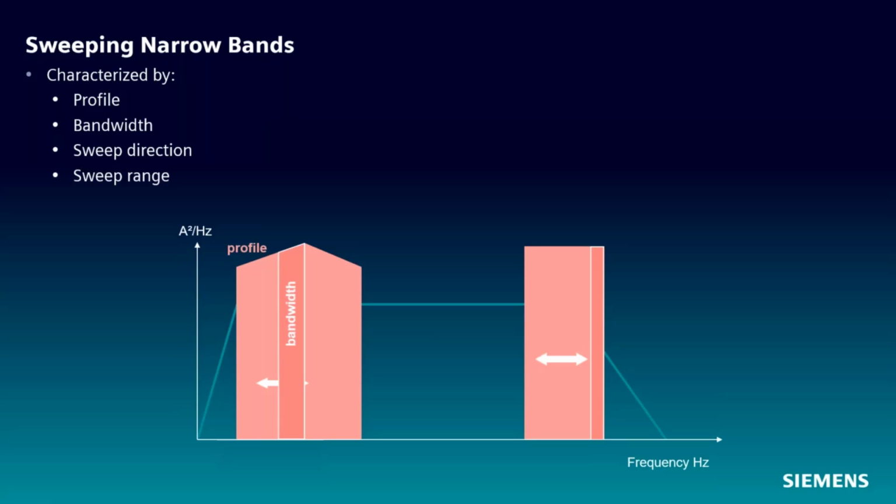Random on random is most typically used for tracked vehicle simulation. So you have tracked vehicles that have a base random excitation due to the engine of the vehicle and road noise. But then on top of that, you have these bands of random noise that are a factor of the tracks themselves and how long the links are and how fast the vehicle's going.